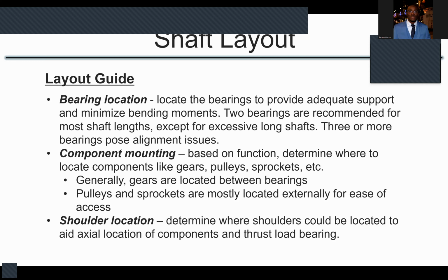Okay. Then your shoulder location, your shoulders should be located where you need your gears and your pulleys to be. Okay, so that when you mount them, they can come all along your shaft and stop at your shoulders, exactly where you want them to transmit their power.